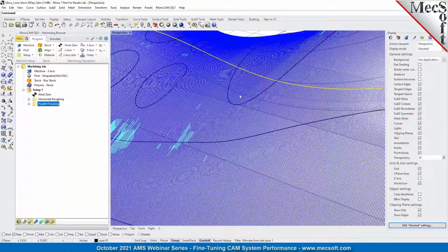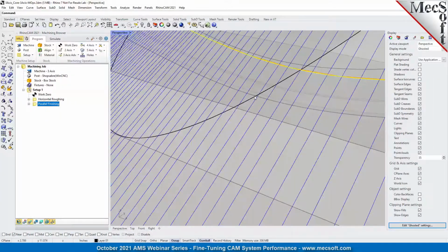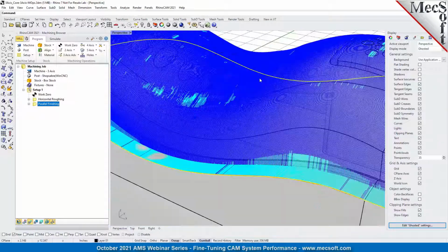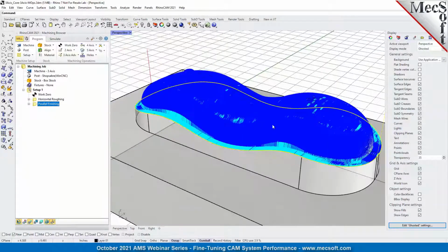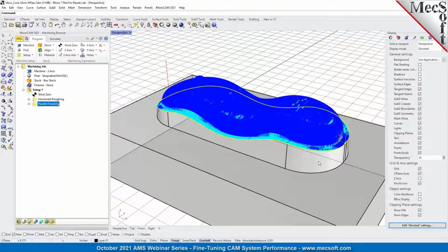So when we do the linearization, the tolerance affects the linearization. And the tighter the tolerance, the more data the CAM system is using in its computation. So it results, like what Don is saying, in more toolpath points, but that's just a side effect. The main effect is it's increasing the data being input into the CAM system.